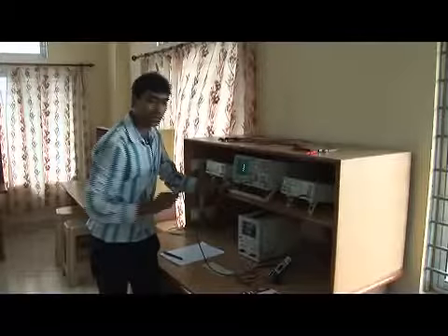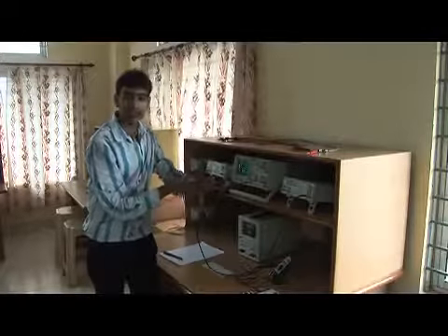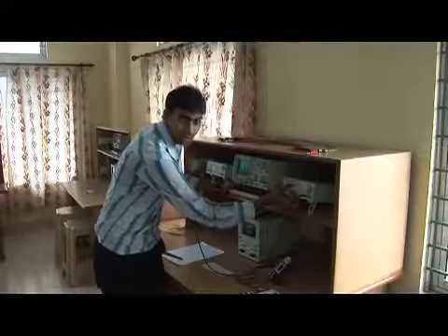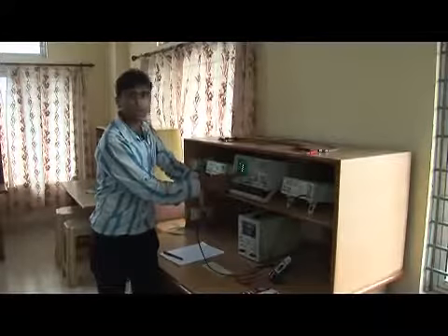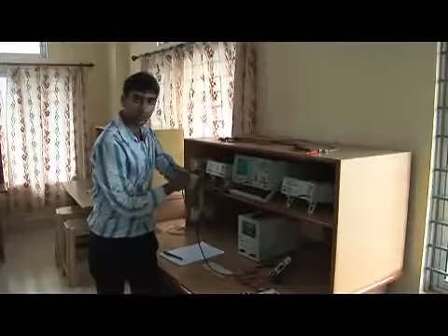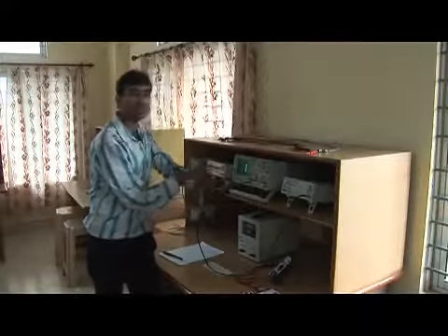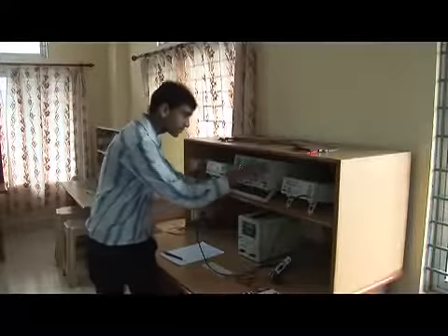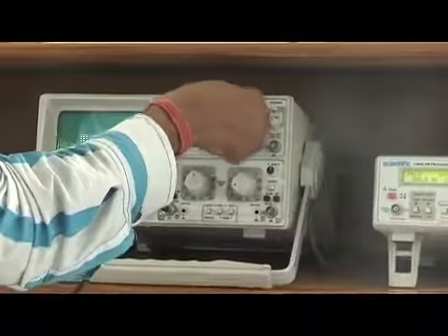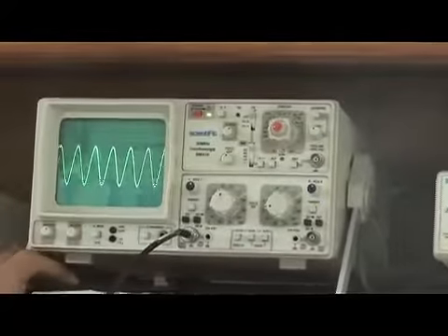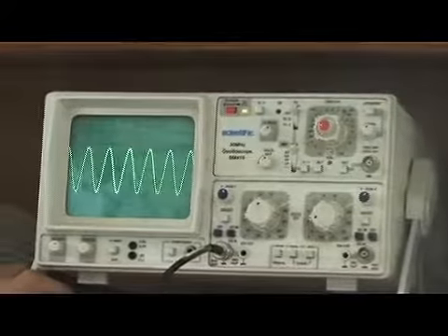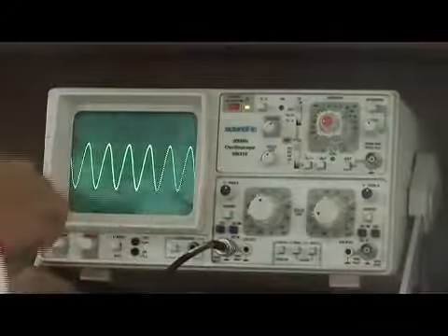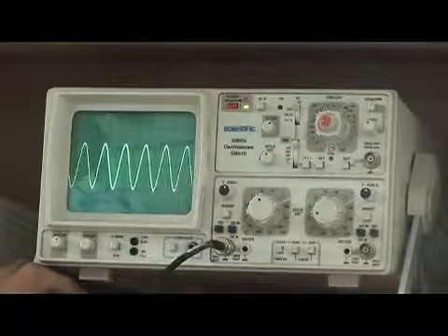Now I have to search for my signal. Some signal is coming, but it's not clear. I have put a sinusoidal here, so this signal should also look like a sinusoidal, but it's not looking like that. So either the frequency is too high or the frequency is too low. In that case, it's moving over here. So let us change its time period. If I change this time period and try to get the signal, we are getting the signal. We are applying a sinusoidal, and what are we getting? A sinusoidal.